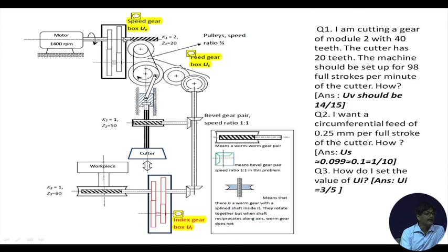After that, at the output side of the gearbox UV, I have this machine element connected with a disc shaped body. What is this? This one looks like a threaded element. Okay, this is a threaded element, and this value of K1 equal to 2 and Z1 equal to 20 gives you the hint that it must be a worm and worm gear pair.